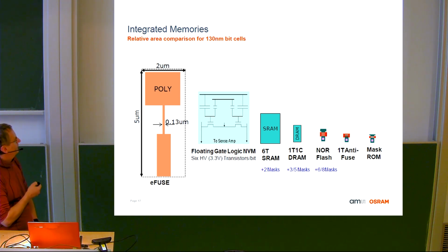And you have then the part which is intended to melt once you program it with a certain current. If you have a logic non-volatile memory, so this is a floating gate memory, this would be, as said before, with a metal line as a coupling cap. So I just used a schematic here, it's not a special transistor, but just scaled it up in the range that you see. It's even better than the polyfuse standalone, but quite large.